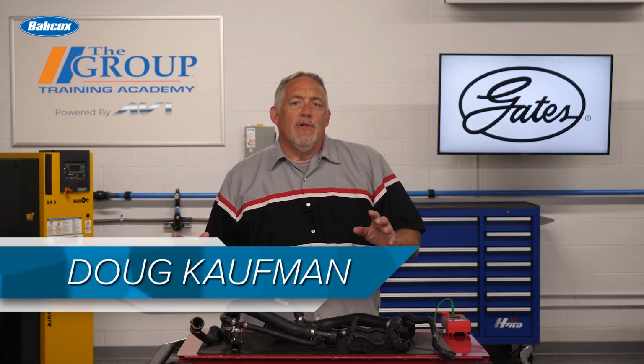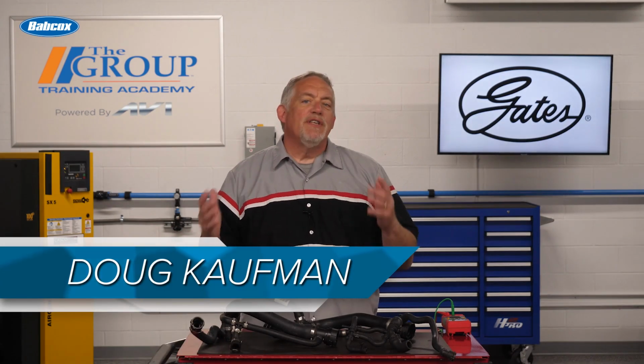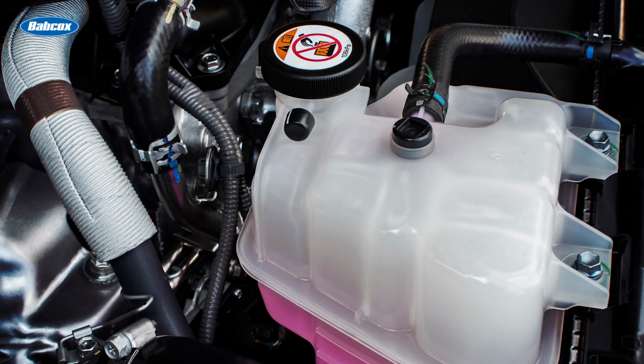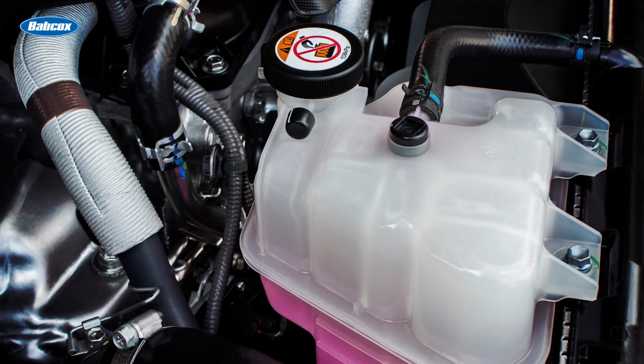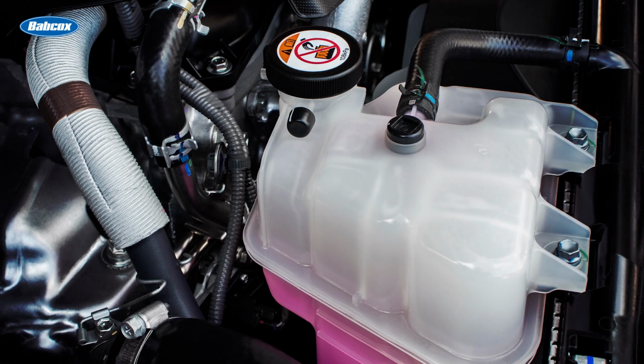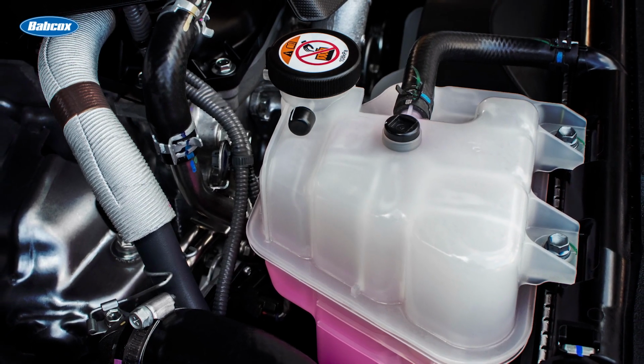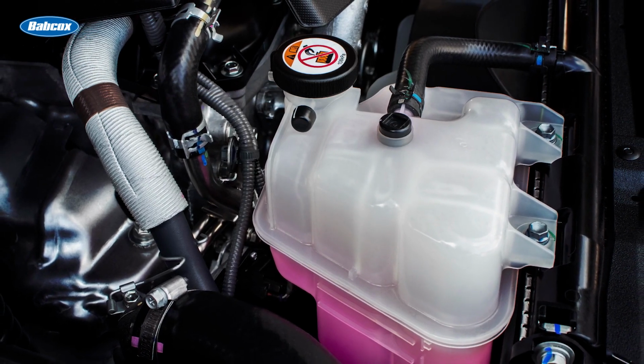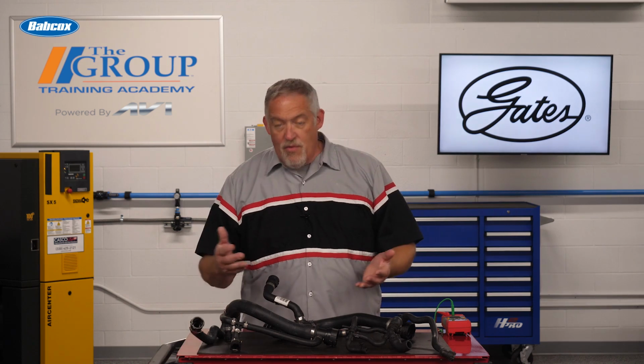Today's complicated cooling systems no longer just keep the engine cool. They must cool and warm various complicated components under the hood, as well as other areas in the vehicle, including the fuel system, forced air induction systems, turbo or superchargers, auxiliary heaters, inverters, and battery packs. To get cooling fluid where it needs to go quickly and efficiently, today's hose assemblies use modular coolant hoses, which have one or more modules built into the hose.